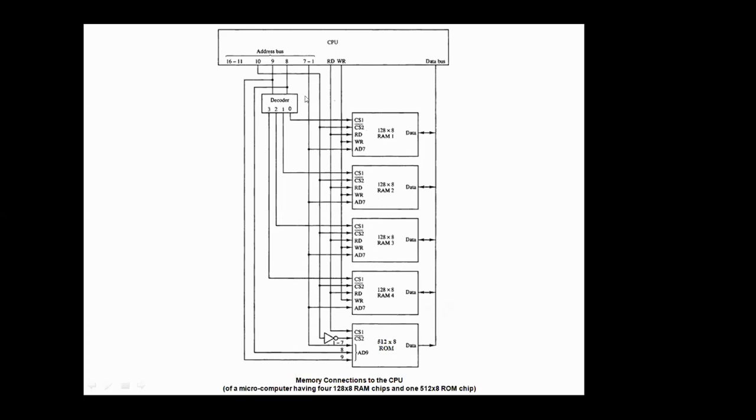So those 2 bits are this 8 and 9. So among the address bus, 8 and 9 will be used to distinguish between 4 RAMs. To distinguish between 4 things, we use 2 bits, that is fine, but an easier way to select one of the 4 is to use a decoder.